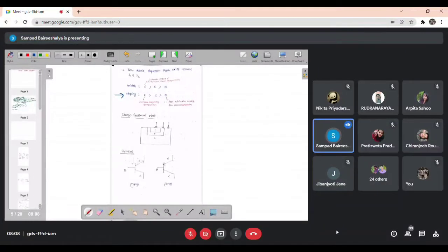तो डोपिंग का मतलब क्या होता है? To increase its current carrying capability, or to increase the free carriers. We are going for the doping, yes or no? हम डोपिंग क्यों कर रहे हैं? To increase the conductivity. Increasing conductivity means generating more number of carriers. तो हमें अभी पता चल गया कि इमिटर से हमको ज्यादा कैरियर लेना चाहिए. Okay, that means the emitter should provide more number of carriers.